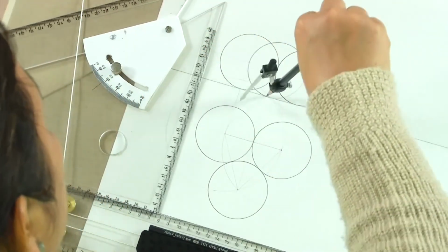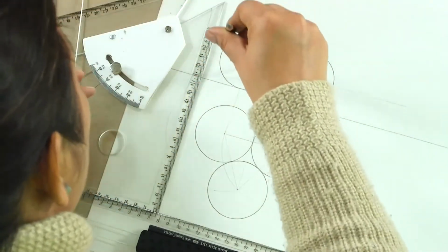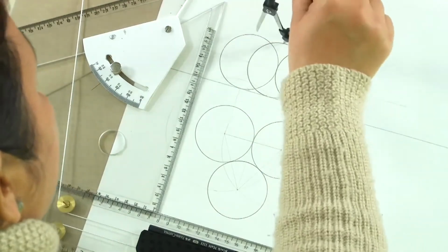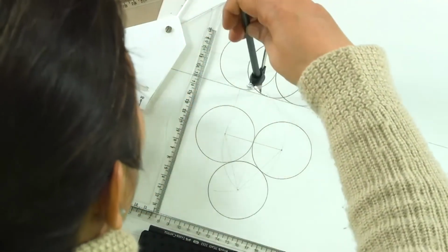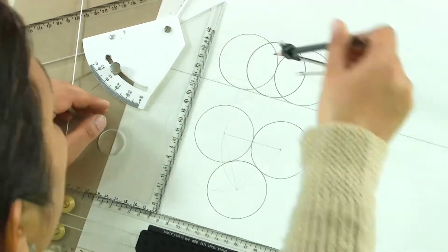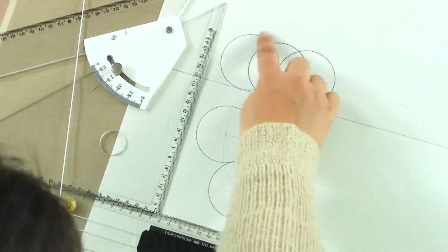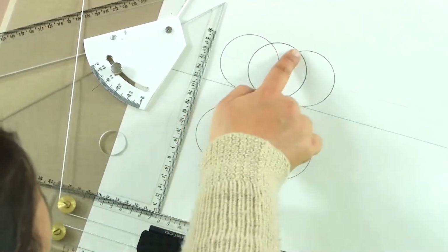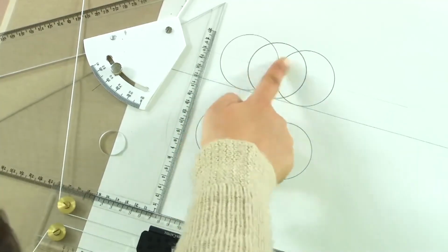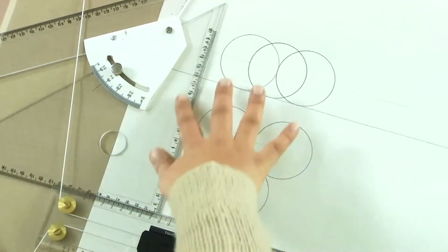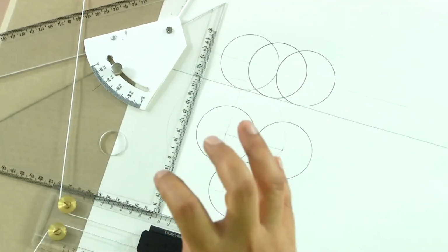Since I am drawing on the existing drawing, I am not making a new drawing, that is why our hidden lines are currently depicted as solid lines. However, if you knew already that there are three spheres and that is how they are going to be placed, we would know that anything which is behind this front circle is going to be hidden. So, these two curves representing this portion behind this are actually going to be hidden. So, that is how it could be any arrangement of spheres which are of the same size.